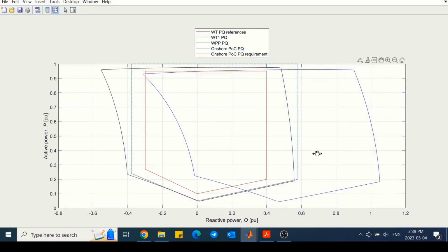When we increase the active power, it means we are increasing the flowing current in the system. The voltage is not affected much, so the reactive power generated by the capacitors will not be affected, but the reactive power consumed in the reactors, which are in series in the system, will increase when the current is increasing.